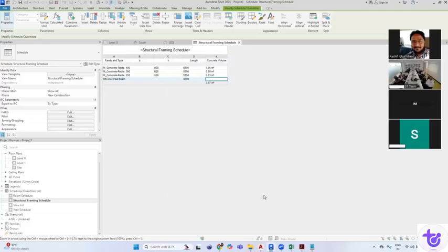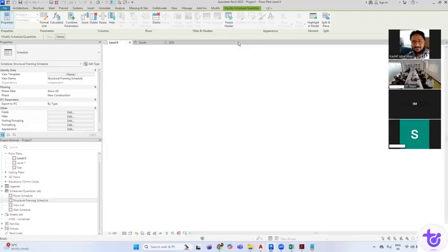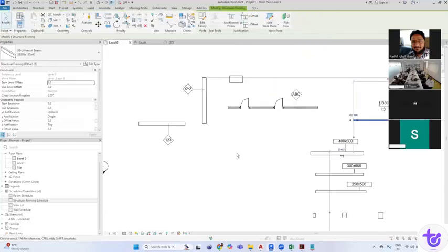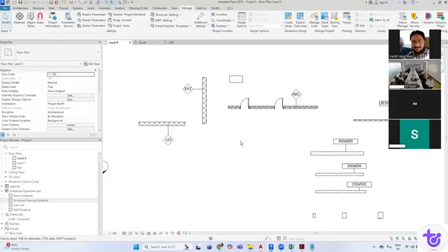So try to do some exercises for the shared parameters, for the project parameters, for the global parameters. Project parameters are also essential to be practiced because we should know what the difference is between the family parameter and the project parameter, how it is applicable to different categories, and how it is differentiated from the family parameter. It is always used.